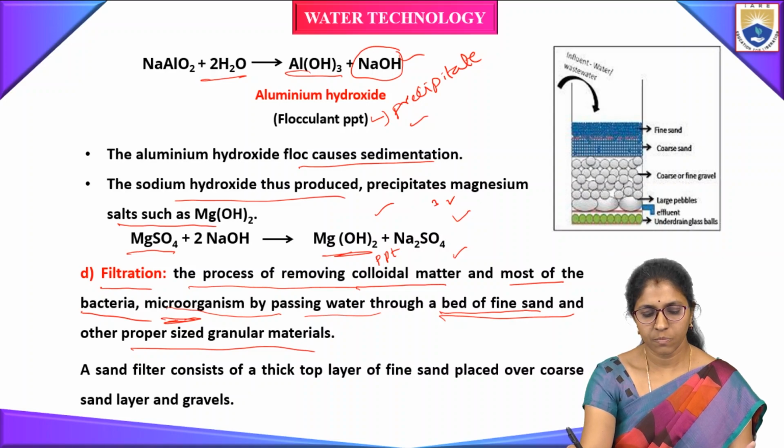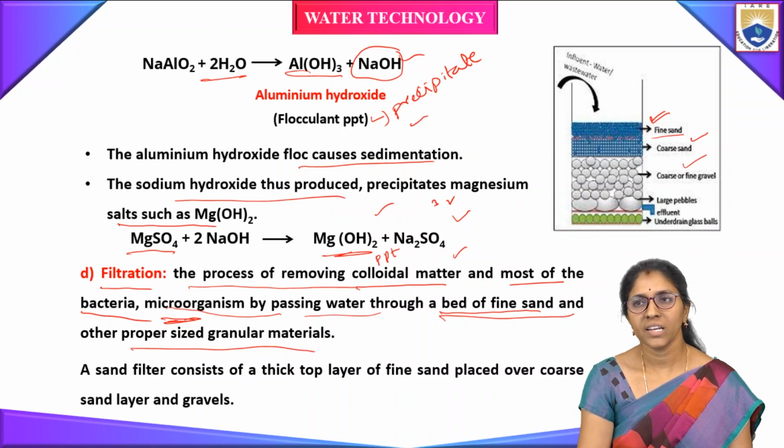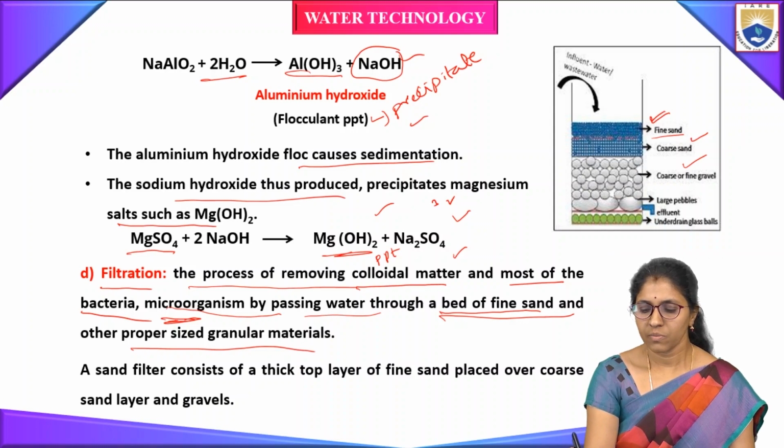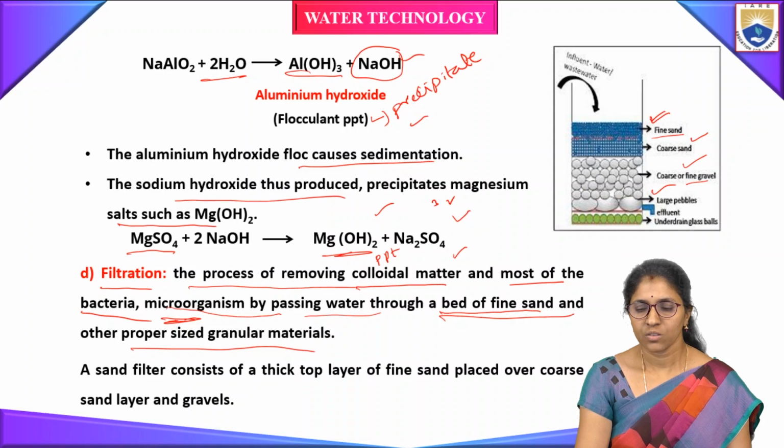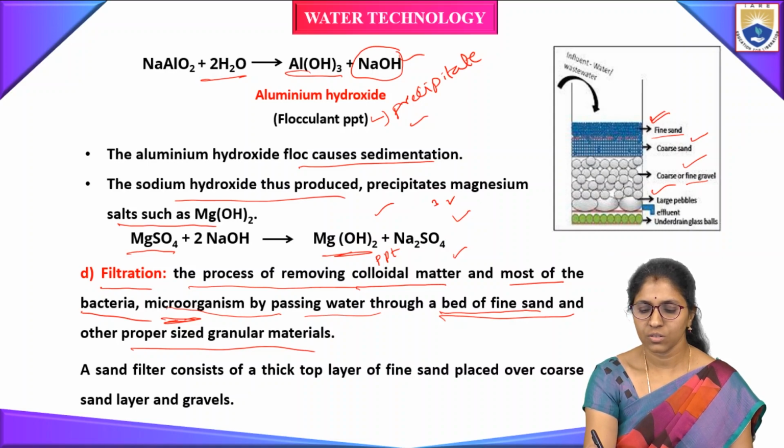See here, this is a filter. In this, the fine sand layer is placed over a coarse sand, and this coarse sand is placed over coarse or fine gravel. So this coarse gravel is placed on large pebbles. So this is the construction of a filter.